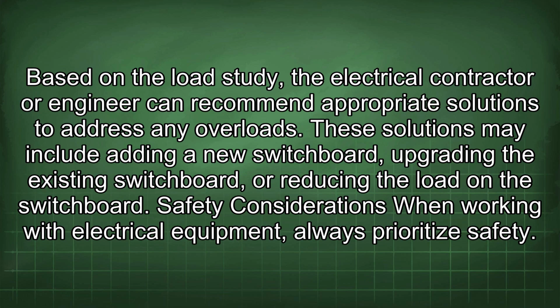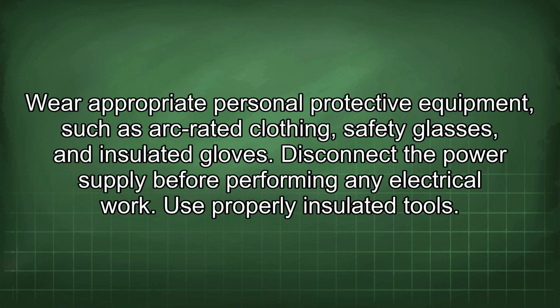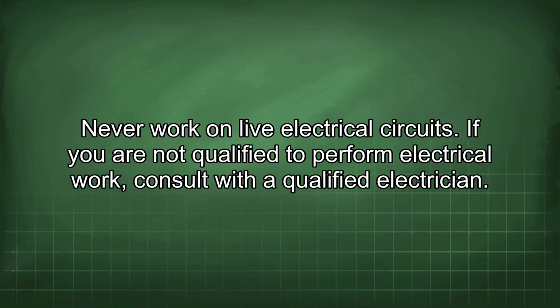Safety considerations when working with electrical equipment. Always prioritize safety. Wear appropriate personal protective equipment, such as arc-rated clothing, safety glasses, and insulated gloves. Disconnect the power supply before performing any electrical work. Use properly insulated tools. Never work on live electrical circuits. If you are not qualified to perform electrical work, consult with a qualified electrician.